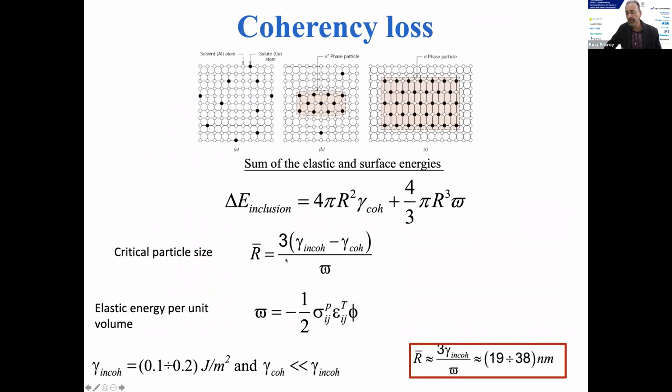And if you allow them to grow with thermal energy, grow too much, then you actually lose this coherency as they grow. Something very similar is happening to our system, of course, not by heating or by cooling, but by going through an amorphous phase, which is supersaturated, of course, in magnesium. It crystallizes, you have high magnesium in the lattice. We'll soon talk about how you get these nanoprecipitates.